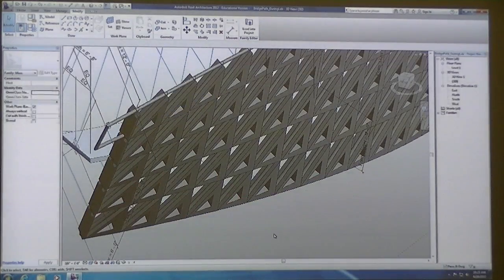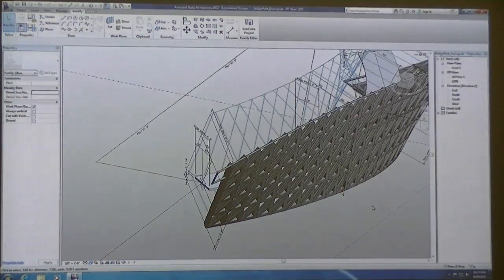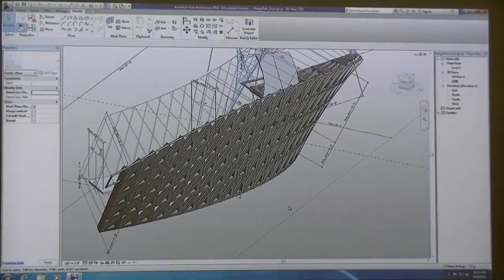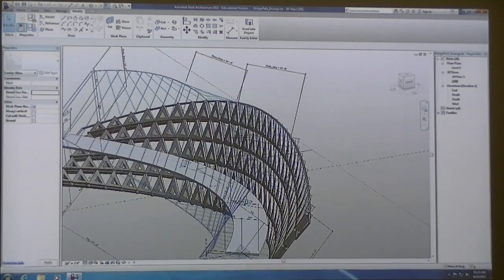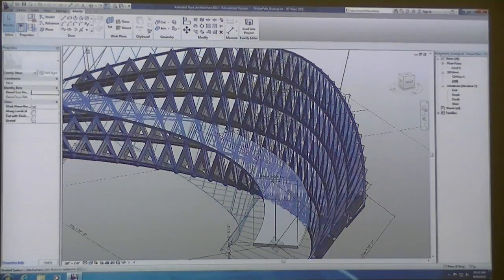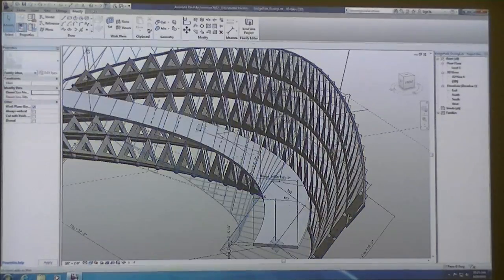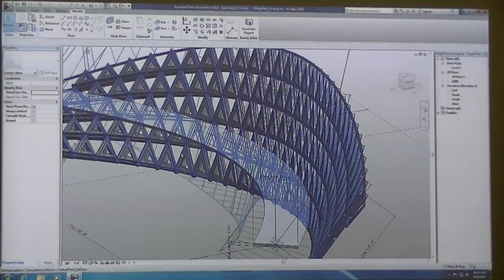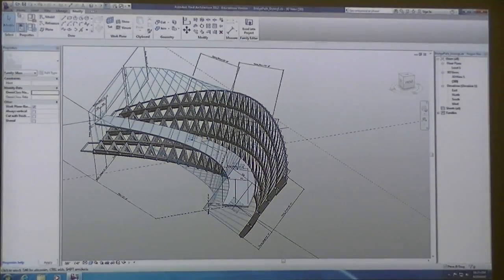So now I've got this, it's a little out of scale, but I can go back in and tweak my parameters, and I've got my curtain panel applied all the way across this particular path. So now when I look at my bridge, I've got a kind of a complex structure off to the right. Could be kind of a canopy or like a screening device as you walk across the salon from one side to the other.